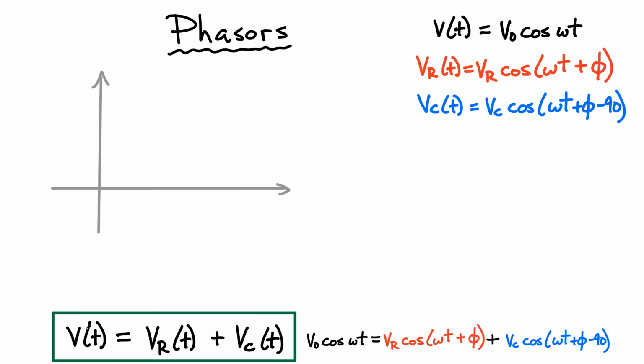So what we want to do now is start solving things. We want to solve for the angle phi that appears in some of these terms, and we also want to find the maximum current, which appears in here, and that will enable us to solve for these amplitudes. Everything comes down to solving Kirchhoff's loop rule over here, which led us to this expression. If you substitute the voltages into this equation in the green box, you get the expression down here in the lower right-hand corner. Now we have to solve this equation for phi and also for I max, which appears in both of those terms. That's actually pretty hard to do. You could use some trigonometric identities to break these terms up.